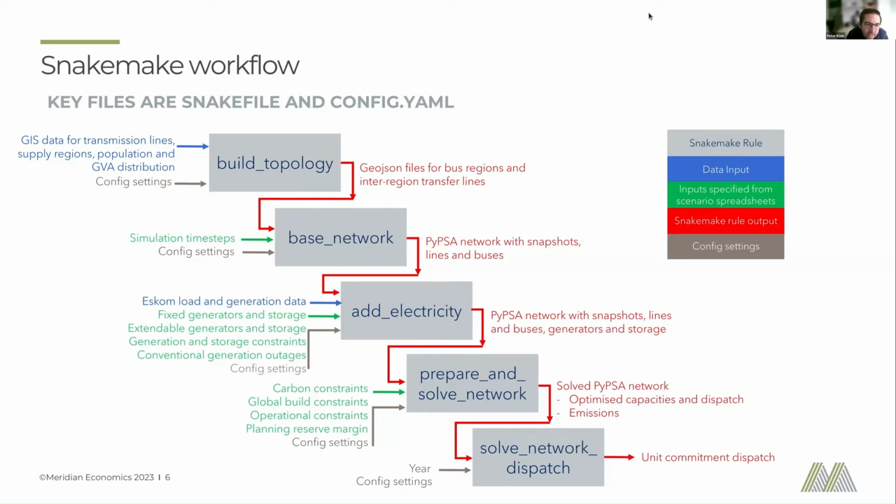And you'll find quite quickly, especially if it's printing out the convergence criteria, if, for example, it's been running for 2 or 3 hours and it's only done like a couple of steps in convergence, that it's unlikely to solve within 24 hours or more.